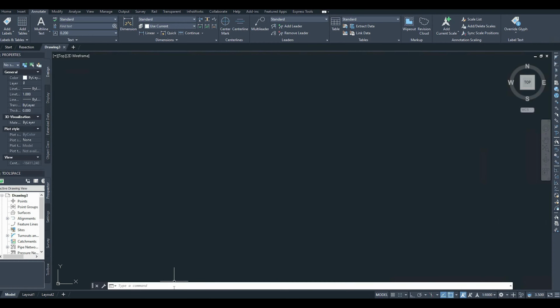So here in the command bar in the bottom here, guys, just very simply write down point and then enter. Now it's asking for its coordinates. I will provide the coordinates. We know them. So the easting of control station A, 9169.900. I would add after that comma, guys. Okay, just watch here in the bottom, the command bar.